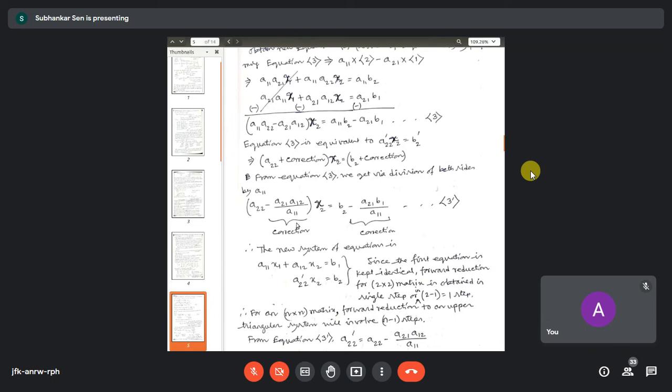The central difference scheme will give you unstable or meaningless solutions if your grid is not very fine, okay? So for these convective terms, we don't use the central differencing scheme. If we want to use it, we have to satisfy one condition on cell Peclet number or cell Reynolds number, okay? If we don't do that, then these numbers may become absurd, okay?